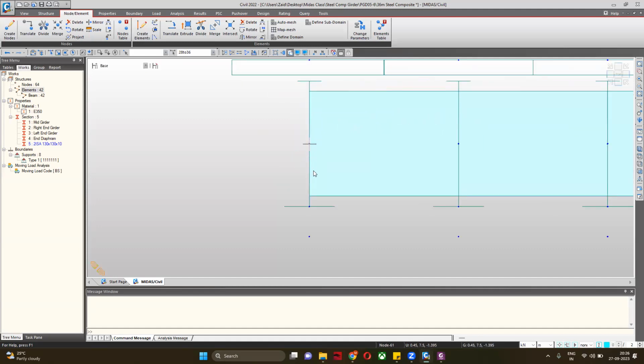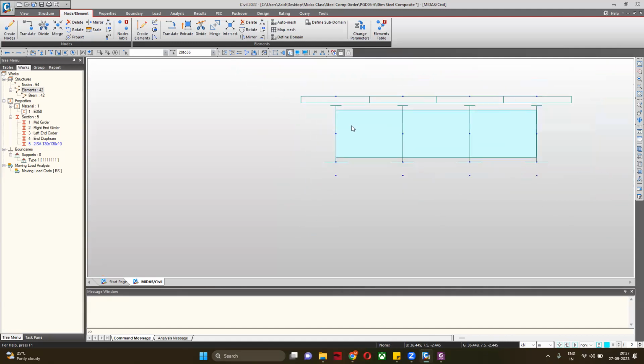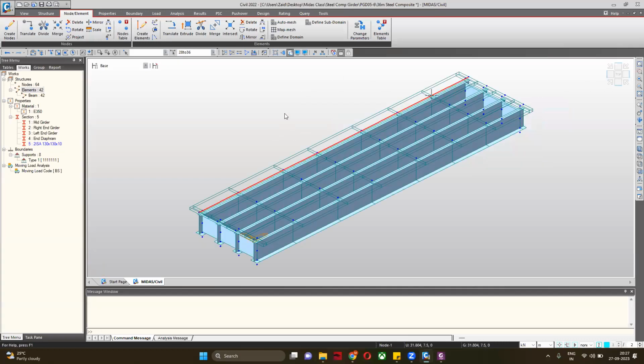We have created a gap here, but an equal gap has been created. It doesn't matter for the shear connection whether you do the connection here or here, because all the force will go by shear force only. The shear force does not create any extra moment. Only vertical shear force will remain. So there is no issue in this kind of modeling. You do not require to put this 2.5% slope, because otherwise your modeling becomes very complex.